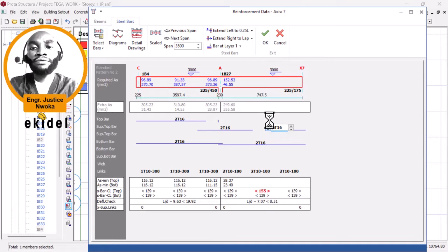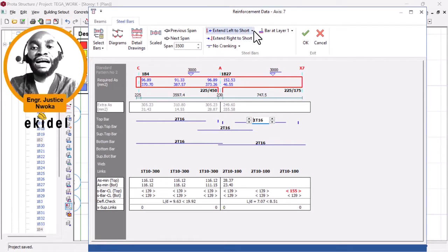So I'll come now and click on it here. Okay, click on this part here, which is to add the main top bar. Okay, and then reduce the bar diameter and then increase the number of bars. First I have to lap to the right, to the face of the cantilever, and then lap now. Okay, that's fine. So with this now everything looks okay, and that's fine.